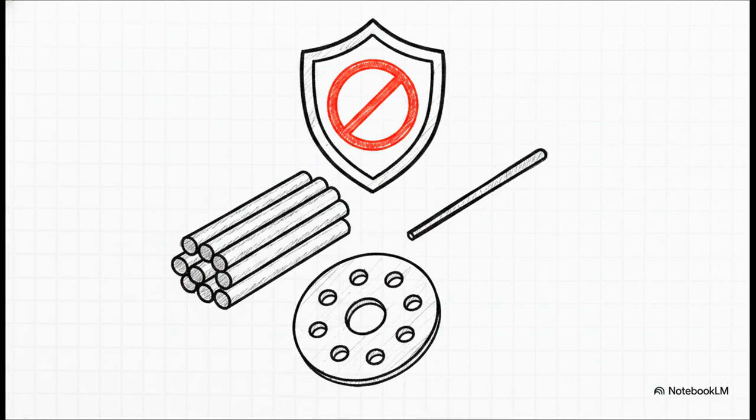Same goes for tubes, bolting, and floating head backing devices under RCB 1.517. Pass partition plates and welded-in long baffles are also exempt under RCB 1.518. And, crucially, all alloy parts, which, remember, means anything not defined as carbon steel or cast iron, do not require a standard corrosion allowance under the RCB 1.52 rule.